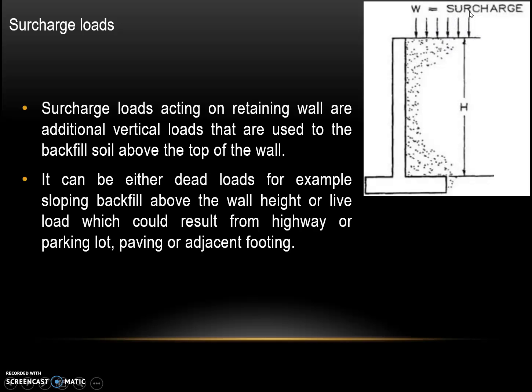This surcharge can be either dead load, for example, a horizontal or sloping backfill above the wall height h, or even live load, which could result from a highway or parking lot, paving or adjacent footing.